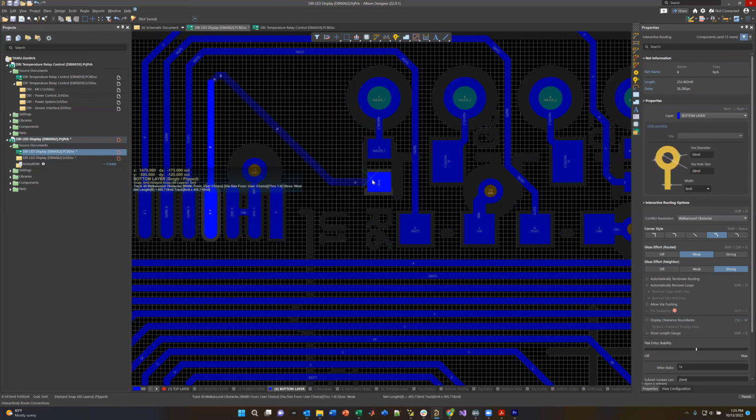So we'll just do it like this. And then technically, so that I can connect the 24 volts here, I'm going to just put a via in and come over here to the bottom side and just connect the 24 volts up to it. Notice what I do here is copy and paste. I have a via style and via size I like, and I just copy and paste.